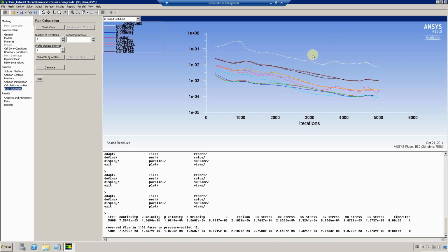The Reynolds stress model might be the most sophisticated Reynolds-averaged Navier-Stokes turbulence model, and the only one able to describe the inner solid body rotation and the outer free vortex in a cyclone correctly. But a downside to the Reynolds stress model is that it is really sensitive to the designed mesh.